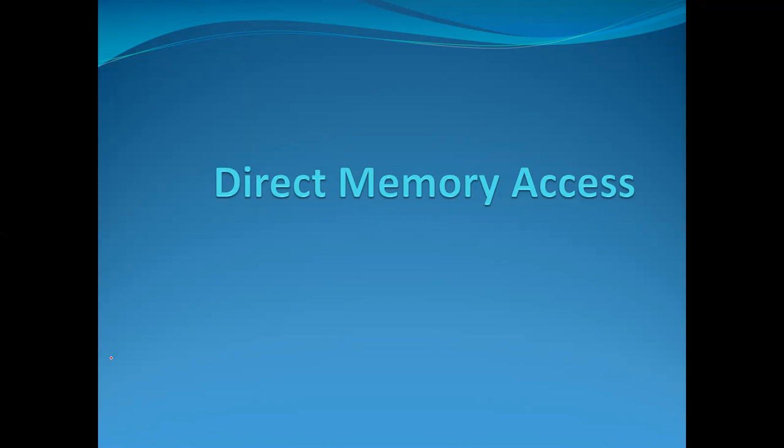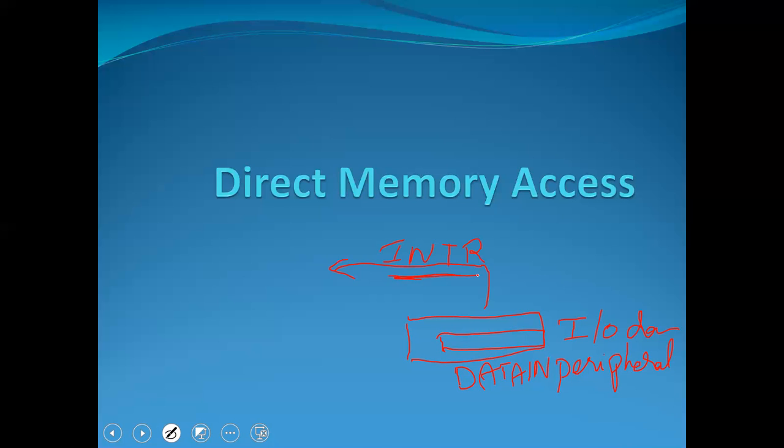Whenever data has to be accessed from input-output devices, also called peripheral devices, how was the data transferred? Whenever the data in buffer or data out buffer is full, an interrupt request signal is sent to the processor, indicating that there is data in the buffer, and the data has to be handled by the processor now.